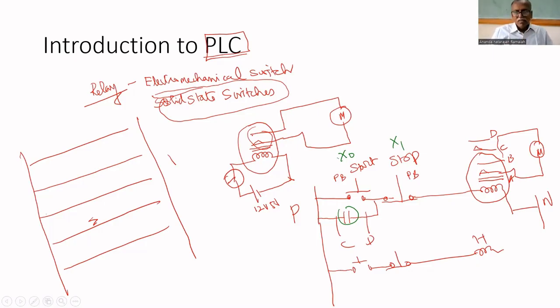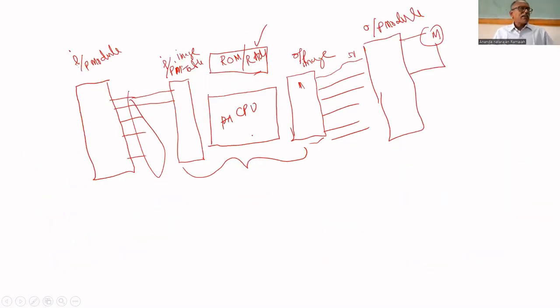For that, the third program. Now we will write a ladder logic program for the same start, stop, a motor and a sealing contact. How to write a ladder logic program? Once a ladder logic program is written, it can be compiled. Once it is compiled, it is like machine language, like what you wrote for 8085 or the 8051 microcontroller. It will be loaded into the embedded system once it is compiled.